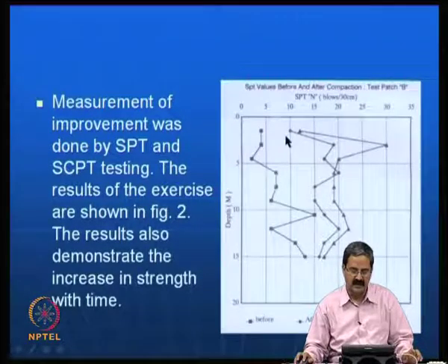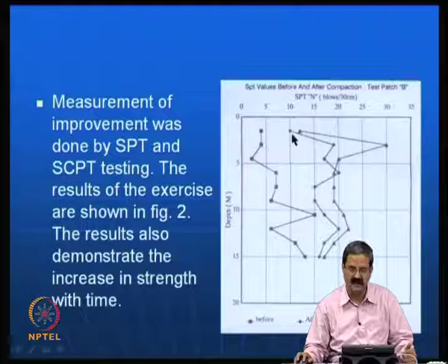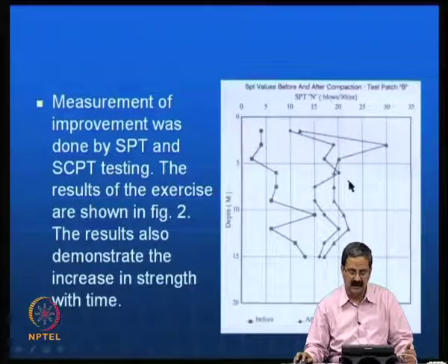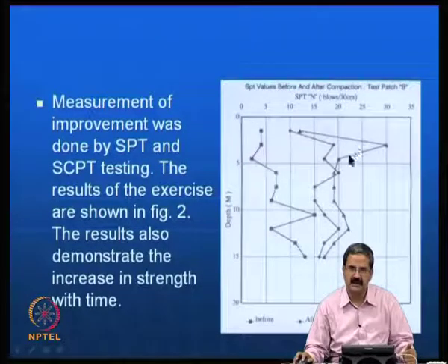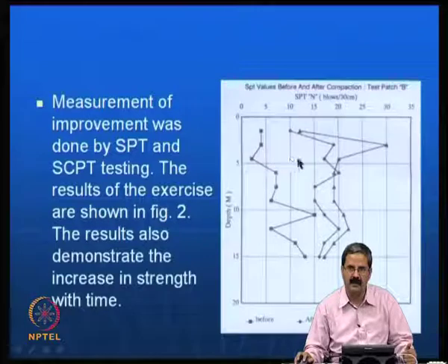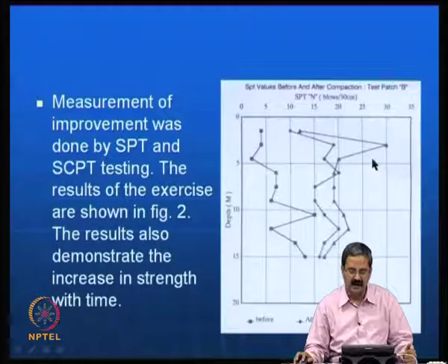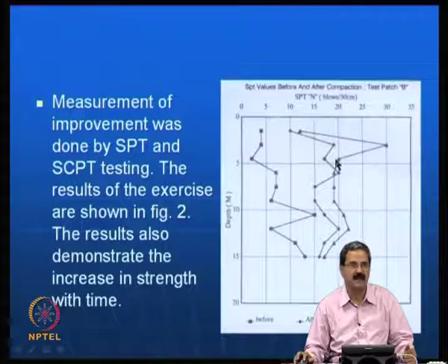Now, after the improvement, they did some testing in the trial section. You can see that the SPT improved to some extent, and it was good everywhere. This point was away from this point, and there is a good difference. One can also see that there is another line: if you take SPT values after 1 month, there is another increase, some more increase.